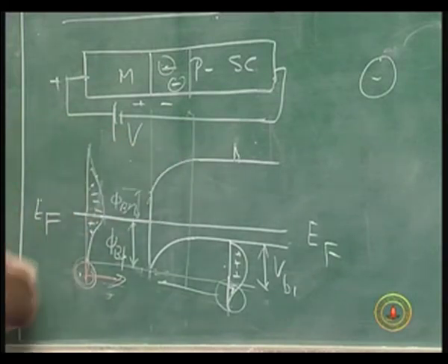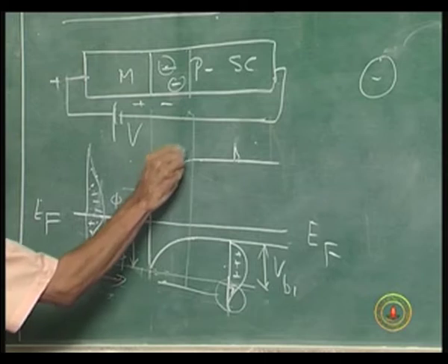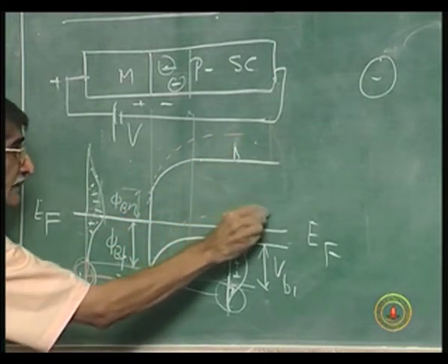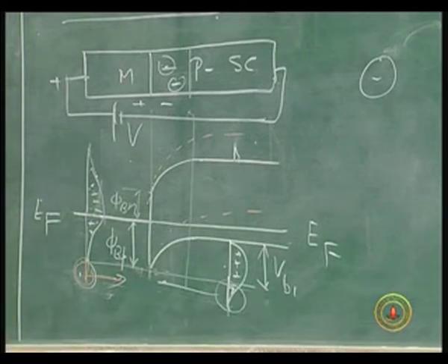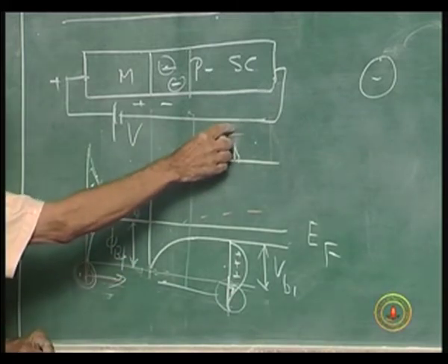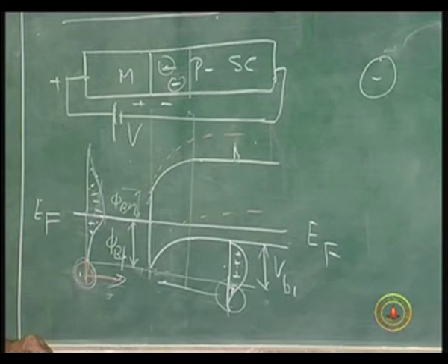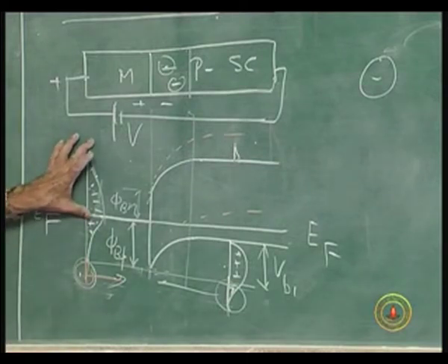If it adds on to that, what happens to the energy band diagram? This whole thing will go up. This will actually go up like this, okay, and this will go up like that. Okay. So, you have the energy band diagram gone up. When it goes up, this will go up there, this will go up there, that is a minority carrier, and this actually is not changing.